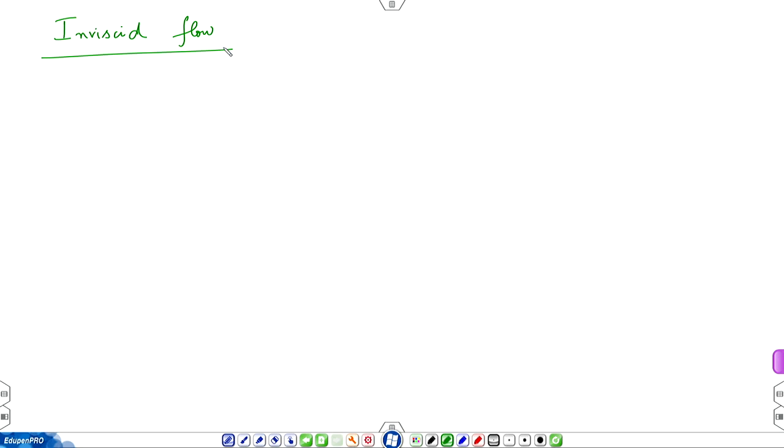So, what is inviscid flow? It is one in which, unlike Stokes flow, viscosity is not important. So we look at the other extreme. Why are we looking at extremes? Because if you work with the full Navier-Stokes equations, you just can't make a start. It's too complicated. So mu is 0, which means Re is infinity. I do not want to say Re equal to infinity, so let me just say that in real terms it is much greater than 1.